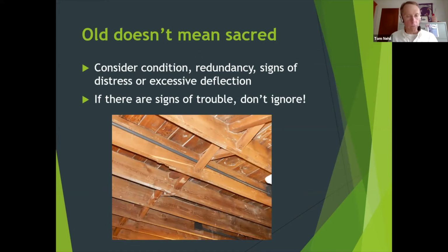Sometimes in our enthusiasm for preserving that historic fabric to the max, we want to grandfather the whole building in and just say it hasn't hit the ground yet, so isn't it okay? I don't consider that reasonable. If you go into a building and you see broken joists or badly sagging floors, that's an indication of probable trouble. And if you've got signs of trouble, and if the calcs aren't bearing out for you, then you probably need to do something. I think you must.